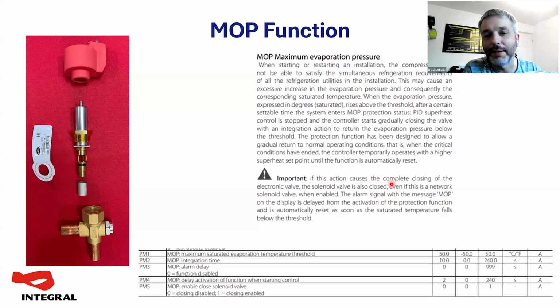suction pressure. Yeah, absolutely. And if it so happens you hit MOP when your valve is shut, that's the point you'll stay at. It just won't open at all, and you'll end up eventually with all the valves shut.